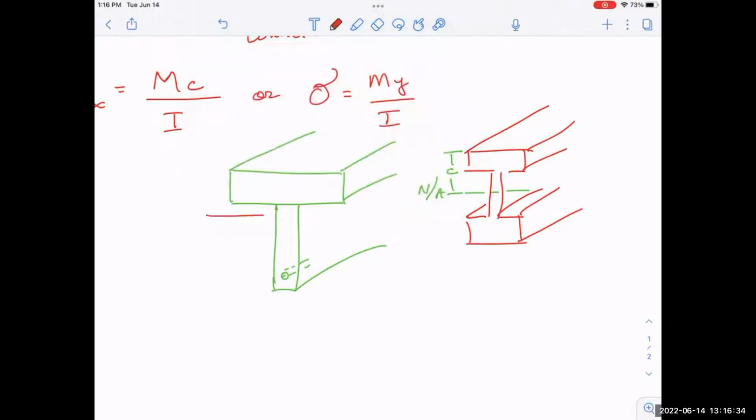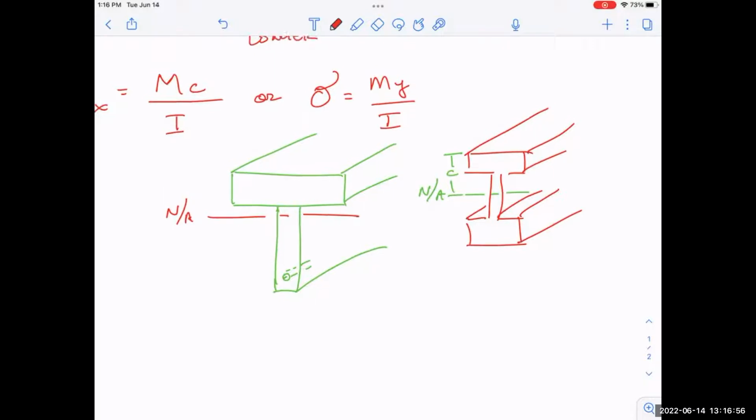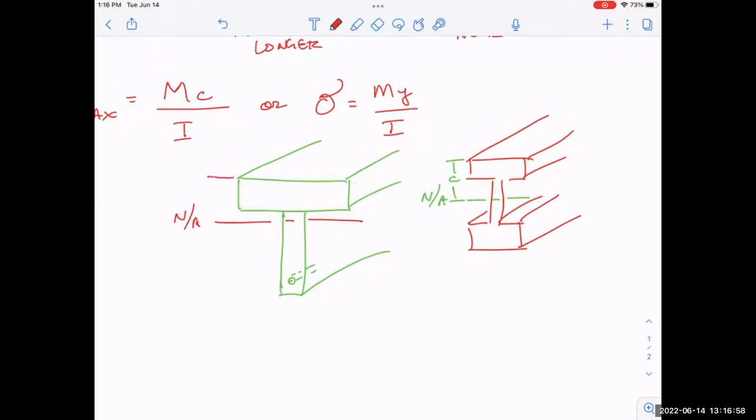But see, the problem is, does it make sense the neutral axis in this example is going to be pulled way up higher, thanks to the fact that there's a bunch of material on the top? And with respect to neutral axis, what we're really talking about is just where the area matches up. In other words, you've got area on the top, you've got area on the bottom, and that area matching up is kind of the gist of it. It's a little more complicated than that. And so we've got to calculate this neutral axis, but it isn't always going to be so simple.